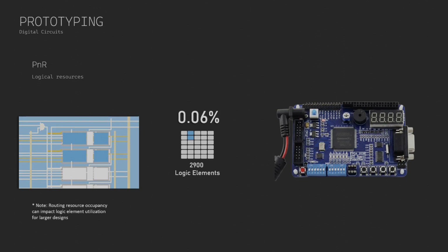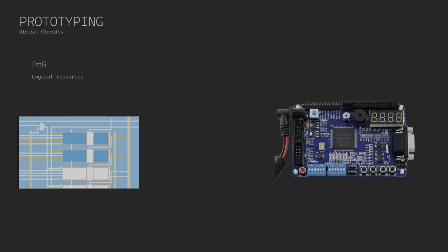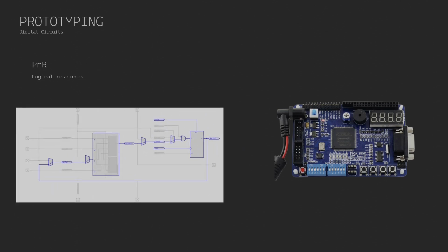So you can see the advantage of FPGA over the breadboard implementation here. If we zoom in further, we can see the lookup tables and registers to which our digital circuit is mapped and routed. The synthesis and PNR require many input files along with our HDL code, which can constrain the design for power, area, and performance optimizations. I am happy to make one more video fully dedicated to it in future.